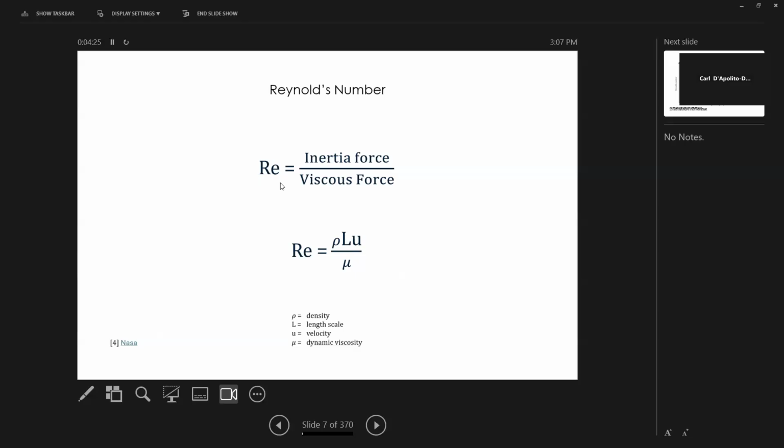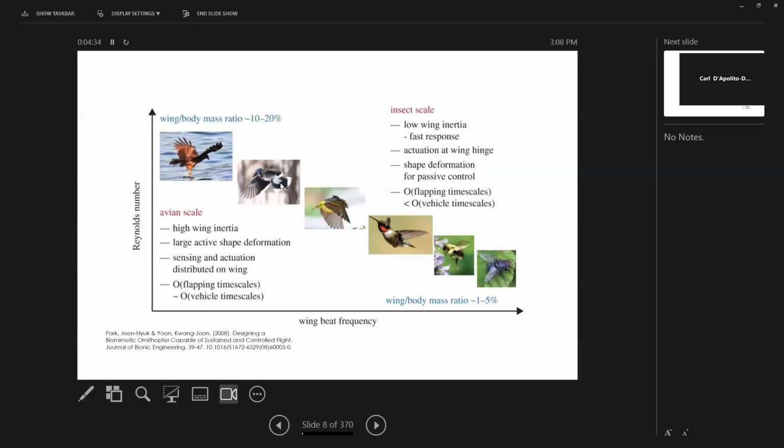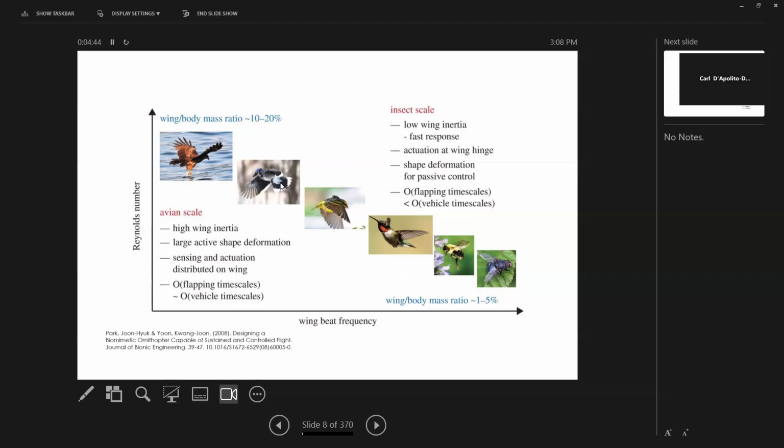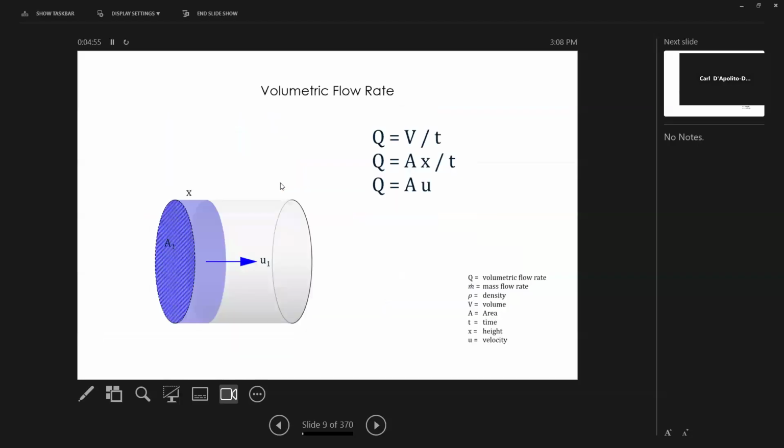And that is something that you measure, and that you cannot change in a wind tunnel where you can't control the temperature or the density. The Reynolds number is just a criteria you can use to apply to any particular situation. So you can say something's this big and going this fast, in this type of material, it has that type of Reynolds number, and then you can predict whether the flow is going to be turbulent or laminar. Almost all flow is turbulent.